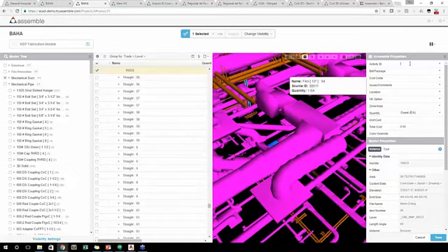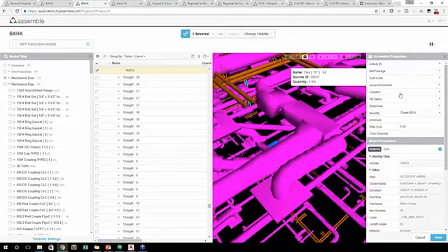And ultimately, that information can be exported out and shared with Excel. So any of those properties that maybe you group your information by within your AutoCAD models, you're able to take downstream and export to Excel. You can also change those Assemble properties within Excel and import that back into Assemble.